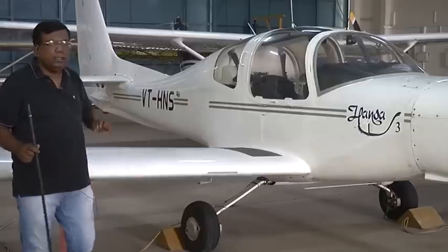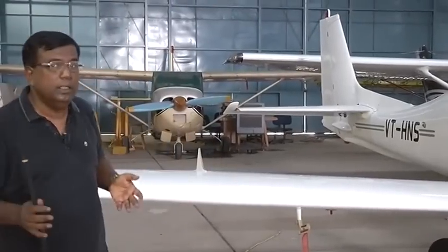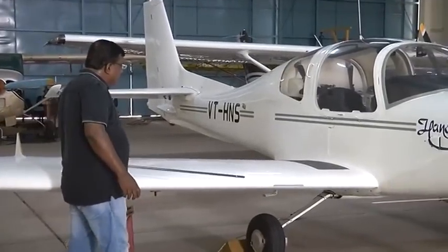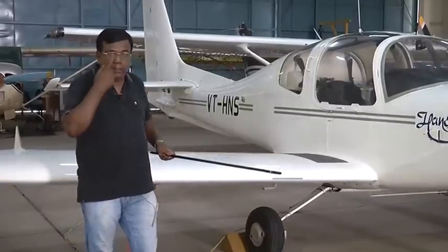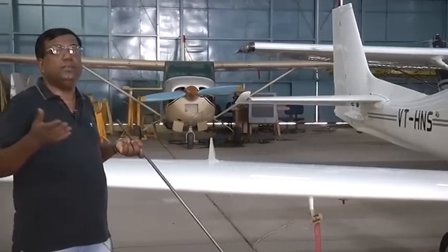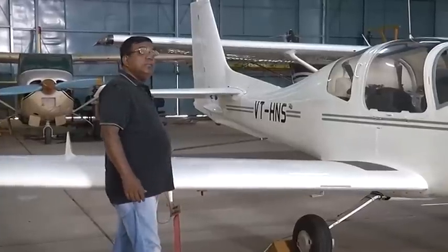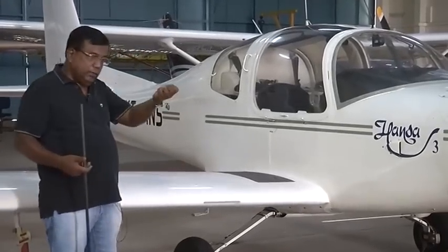So that boundary layer thickness, it's not a huge boundary layer for the wing, but it depends upon something which I call the Reynolds number. Please understand, when a fluid is flowing over this, it has an inertia associated with the momentum of the fluid, right? In textbooks, they call it inertia force. So that will try to ensure that it remains in the state of motion. However, because of viscosity, it will try to drag it, try to discourage that motion.